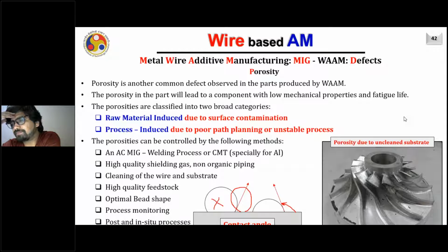Sir, good morning, sir. Prashant here. Sir, actually, as we can see in some of the components like a single cylinder engine, we use sheet metal protective sleeves. So over there, whenever we make that component, we generally use a brazing process, just because welding is not possible on sheet metal because of their thickness. But sir, whenever we join them, there we can face the problem of porosity.